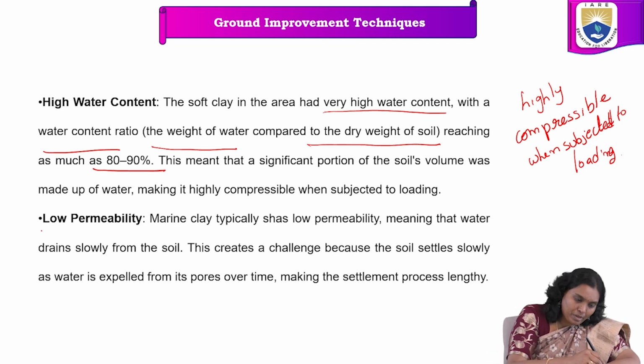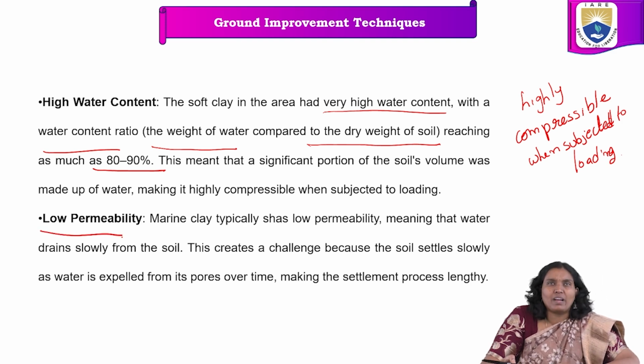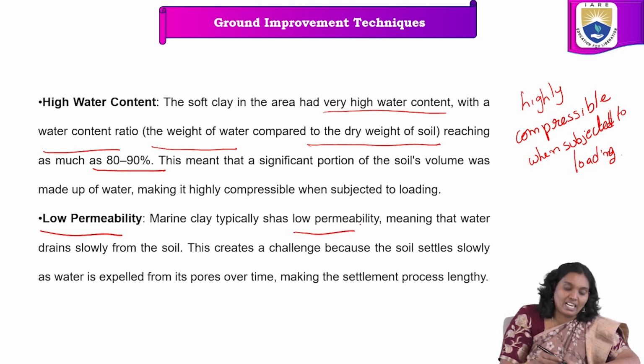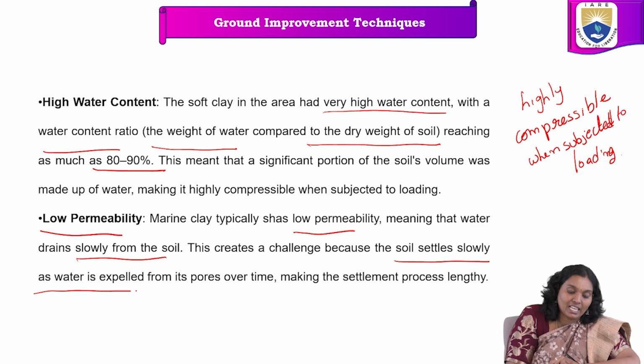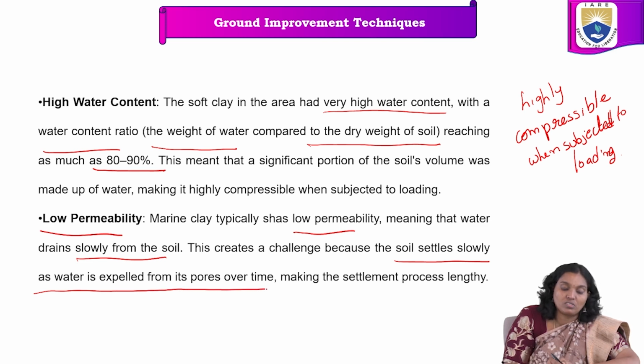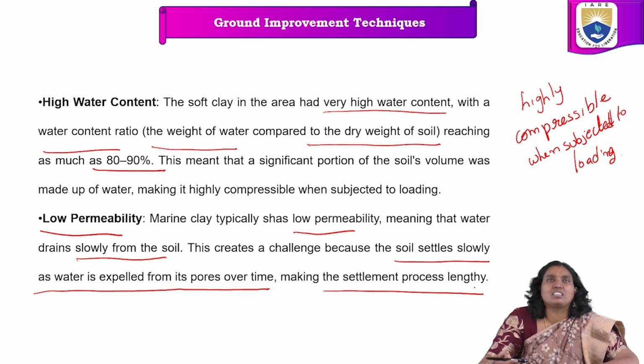In low permeability, marine clay has low permeability, meaning that water drains slowly from the soil. This creates a challenge because the soil settles slowly as water is expelled from its pores over time, making the settlement process lengthy.